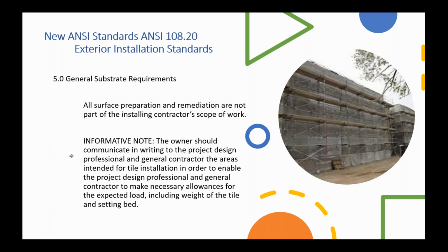That the owner should communicate to the contractor where tile's going so that the project is built properly for it. So you can anticipate the load as well as weight and setting bed. This is an important issue. I mean, if you had a project where maybe they had what they call EQ studs or equivalent studs, steel studs, a 20 gauge stud is not always 20 gauge.